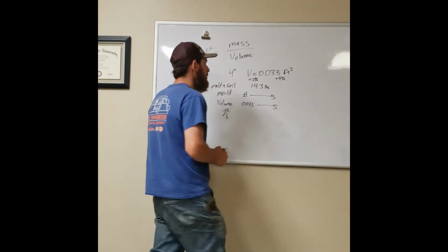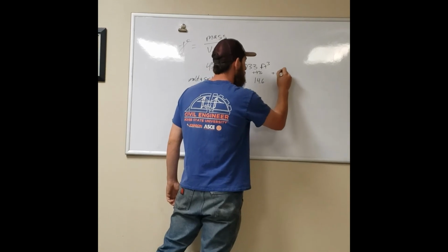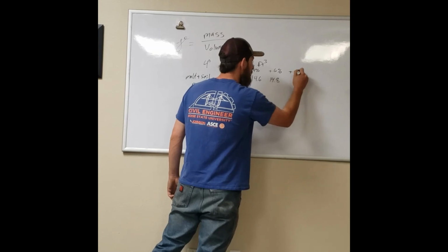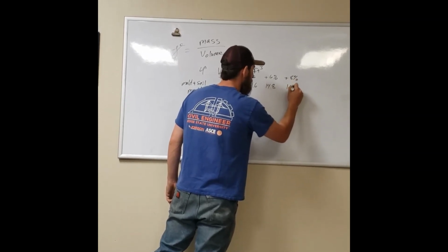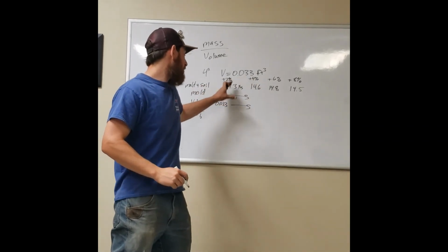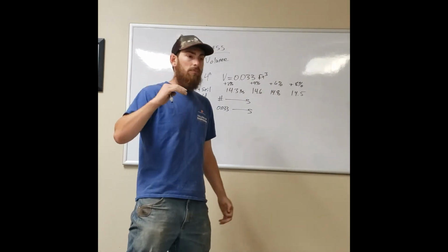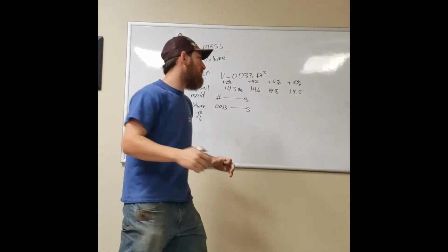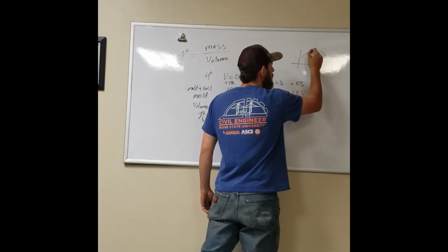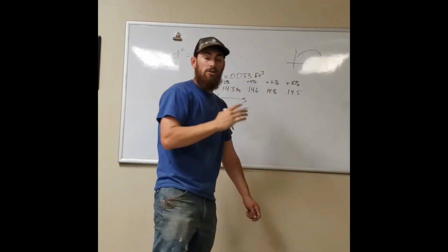So I'll add my 4% and it'll go up a little bit, hopefully. 14.6 plus 6%, 14.8. But then when I get to, let's say, plus 8%, it might drop back down to 14.5. So what happened is my densities were going up and up and up until they didn't. It's not quite breaking over, but we are past our optimum. On this same curve, we got to this point, this point, this point, and then we're on the other side. So now we're down here. That's essentially what's going to happen.